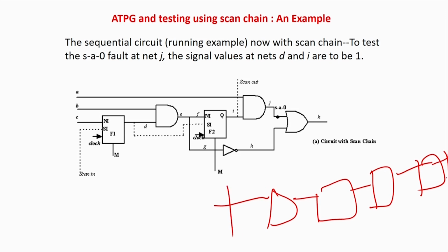Now this becomes a shift register. Once it becomes a shift register, if I require the control of 1 0 1 1, you can easily send a sequence of ones and zeros and fill up the shift register chain. So now the problem has been solved in a very simplistic design manner. In case of VLSI, you always have to remember that complex designs are complex, but the solutions are very simple.